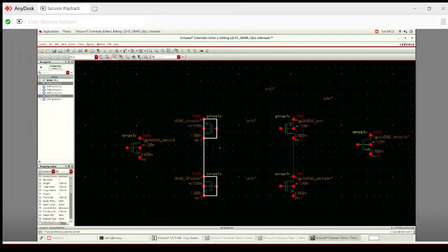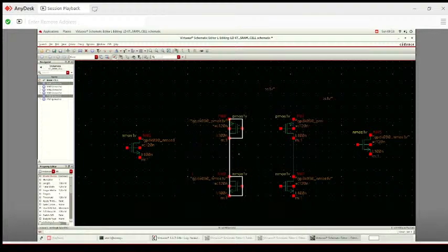So here we are trying to form a bistable latch. Okay, so this distance will be enough. Place it. So let's complete our bistable latch to complete the SRAM cell design. So this is the gate of the second inverter connected. Similarly, the gates of our first inverter will also be connected with each other.